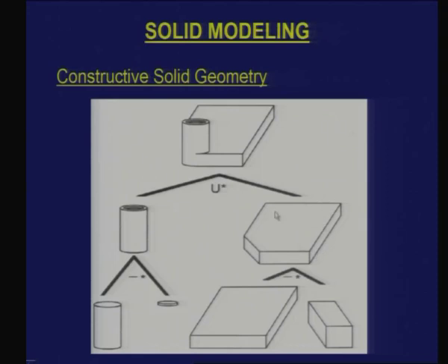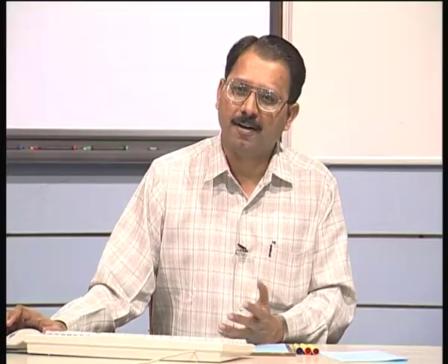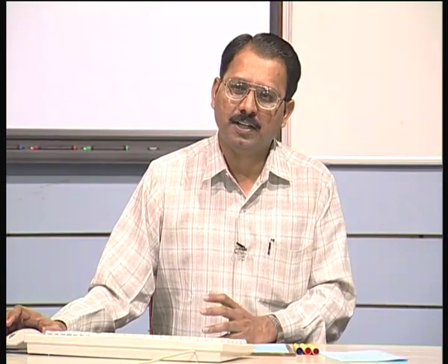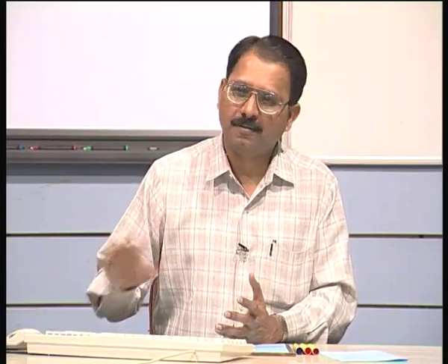First, here is an object which has some kind of wedge shape. I can take two primitives, one which corresponds to the dimensions of this, then another primitive, and place the second primitive with reference to the first. That is important. A difference operation or a union operation is not a scalar operation. It is an operation you are doing on a set, which consists of the points that a particular object occupies in space.